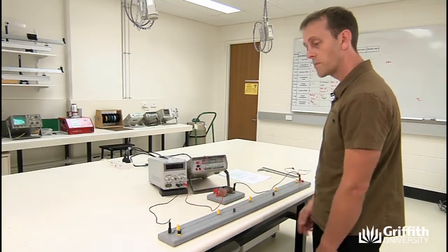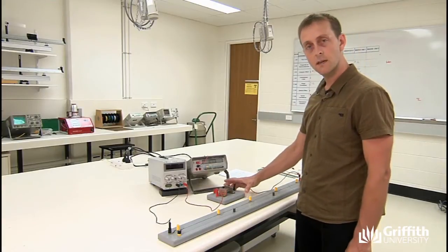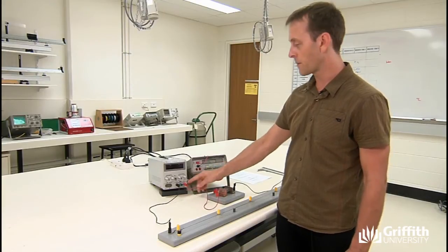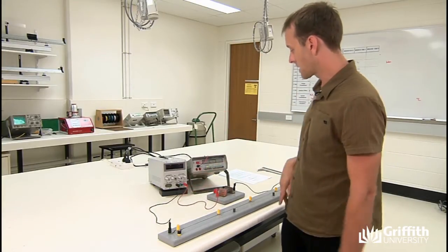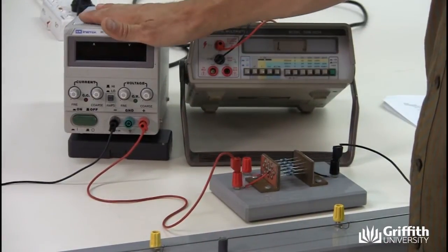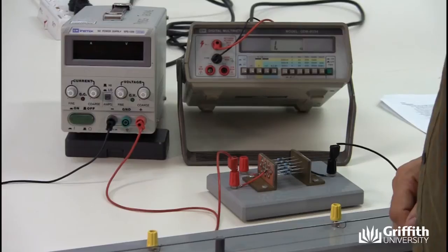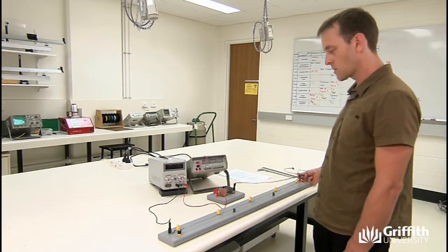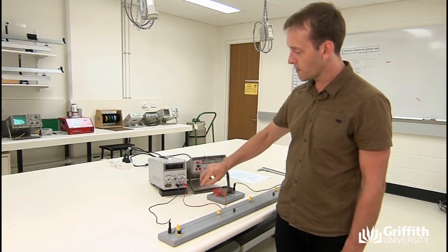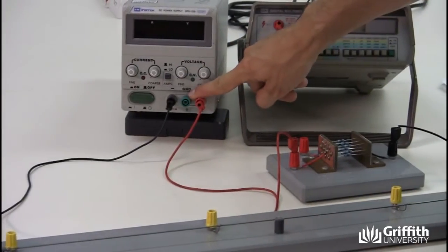We're ready to put some power through our resistor. So we connect it with our standard resistor in line like this. I usually like to use red cables coming out and black cables going back in. It's a good thing to remember. So we've got a red cable coming out from the positive. Remember, your power supply is off at this point, and we connect it to our standard 1 ohm resistor in one end, out from the resistor into our stainless steel long resistor, and then back out to the supply. Make sure that you go from the positive coming out to the negative, don't go to the ground.